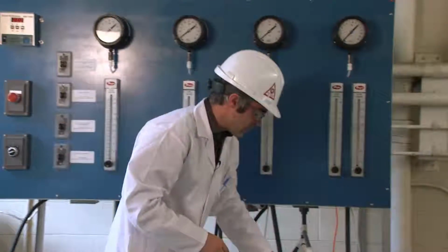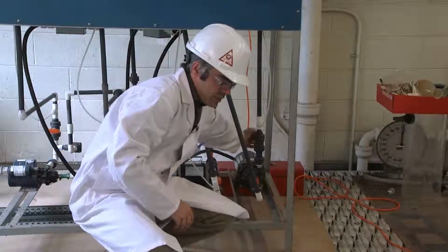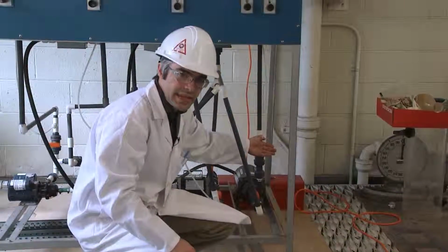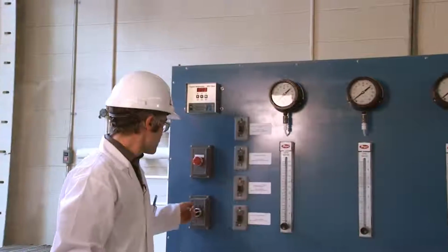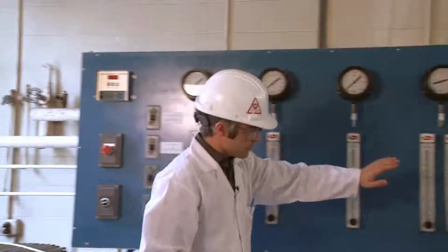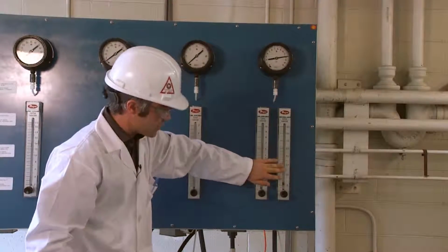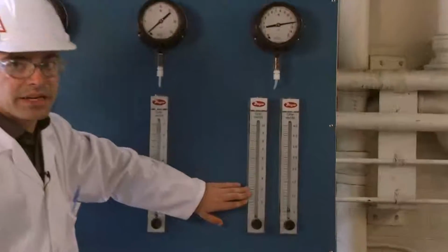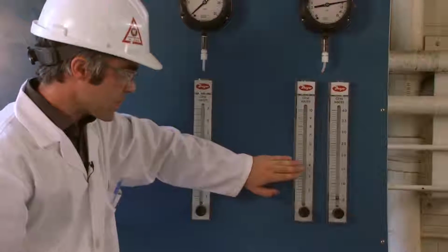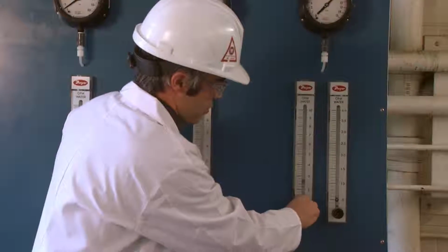In the final apparatus, the centrifugal pump, this is a pump type that we use in multiple unit operation labs for both gas and water. The flow rate to the front of this pump is controlled via two rotameters connected in parallel, similar to the pipe friction laboratory. When using the flow rate, make sure that you have the combined flow from both.